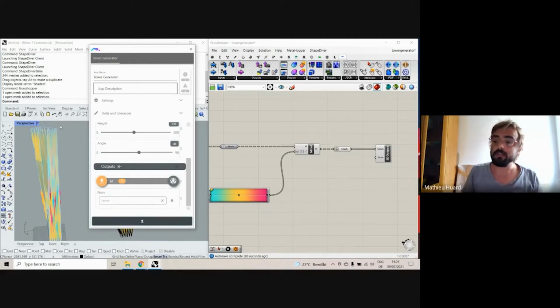But of course, other clients, let's say the web browser, Revit, Illustrator, can store metadata in very different ways too, right? So what we want here is that in Grasshopper, we have a quite generic way to store metadata, which we call attributes in the new plugin, and I'll show you in a minute. We attach these attributes to the objects we manipulate in Grasshopper and send them as outputs of an app. Then all the clients will know how to read those attributes and what to do with them.